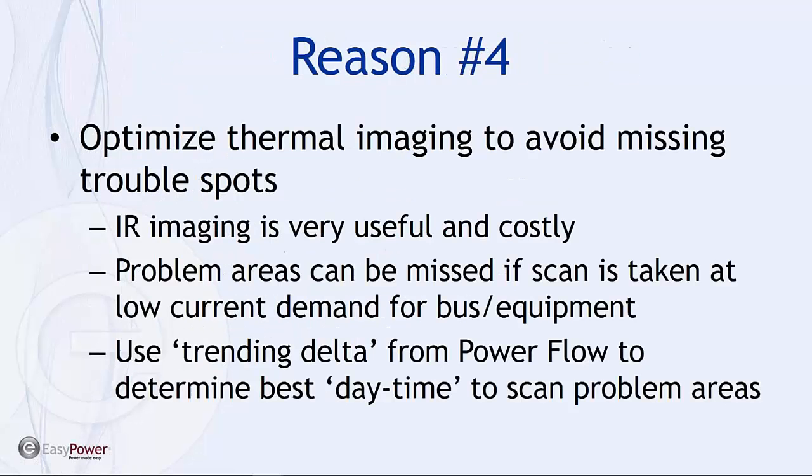We can then do an optimization of some of the other preventive maintenance procedures we may have in place. If we notice losses that we can't justify or explain, we want to schedule those particular systems for thermal imaging to make the operation more productive and avoid missing trouble spots.